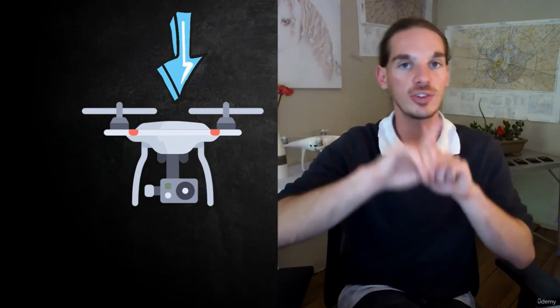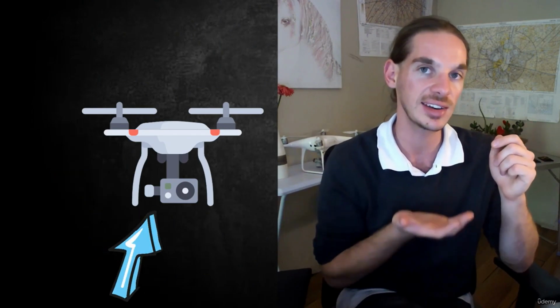You're going to make sure that there are screws in where the screws need to be, and no cracks where cracks shouldn't be. Everything inside your battery slots is safe and secure. You're just going to check everything of your aircraft, and you're going to do it in one fluid motion. You've got to check the top of the aircraft, the sides of the aircraft, and underneath the aircraft. You're going to check screws, the motors, the resistance of the motors, your camera, your payload, your gimbal. You're going to check the wobbliness: is it attached, is it steady, is it going to come off? You're going to check your landing gear.